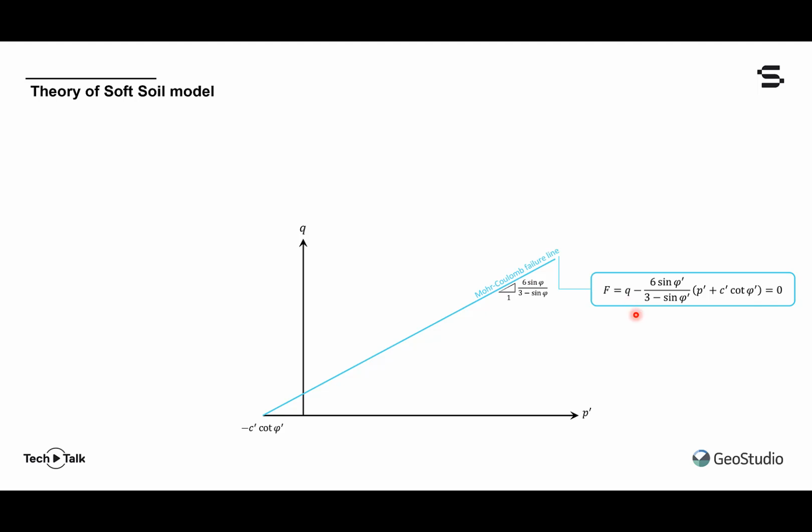Now note that if you access our reference book for static stress strain modeling, you will discover that the soft soil model actually uses a slightly more advanced constitutive law, which is load angle dependent. However, it simplifies to this simple expression of what you would call mu, the Greek letter mu, in triaxial space.